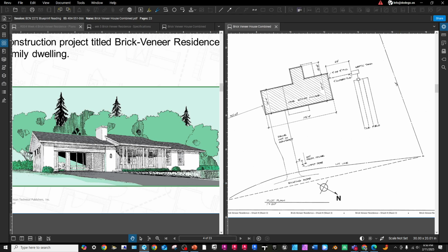So with this being a cul-de-sac, this is nothing but a street with only one outlet and usually a large circular area for turning vehicles. And that turning radius must be calculated when being designed. Usually it's going to be designed for, especially here in Florida, at least a fire truck turning radius. Okay.